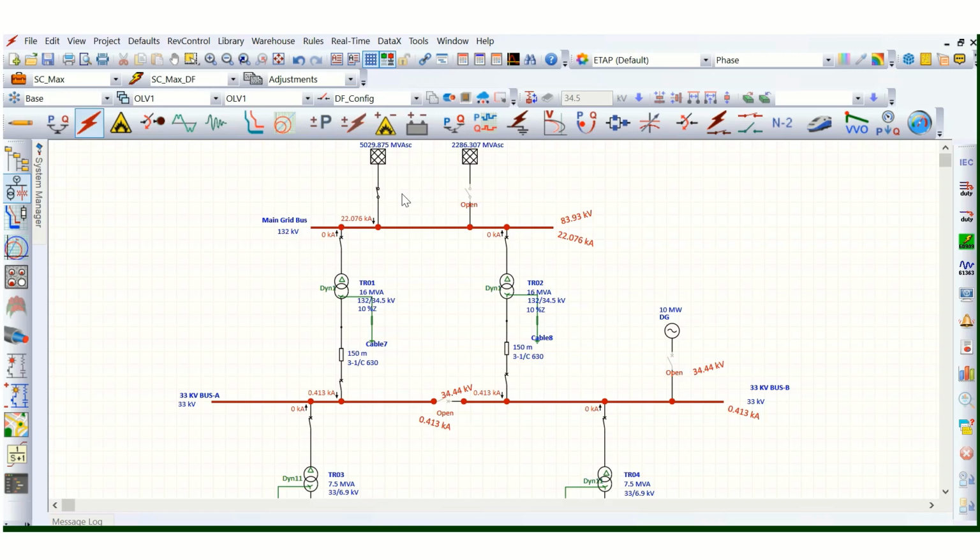because at 400 kV system level, if it is a solidly grounded system, the neutral grounding fault current will be higher, and there the protective relay will trip within 3 to 4 cycles, that breaker will trip. Actually the fault will be cleared, that means within 180 to 200 millisecond, the fault will be cleared instantly.